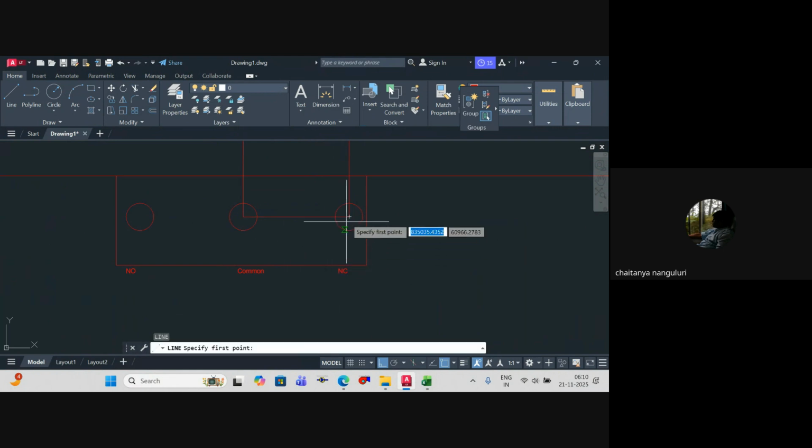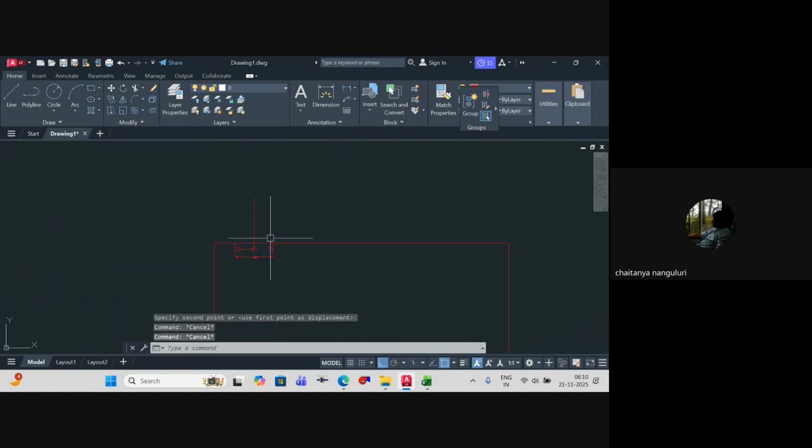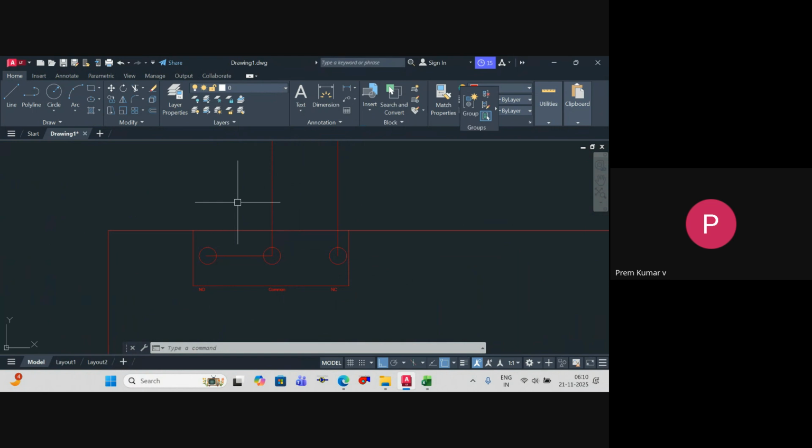And instead of these two, normally open and common will be in contact with each other. That means initially if the circuit was closed, the circuit will be open. But if you connected NO and common, generally it will be in open state, but whenever there is a fire, it will be in closed state. Understood or not? The circuit wise. Yes. Okay.